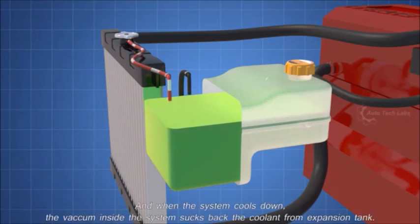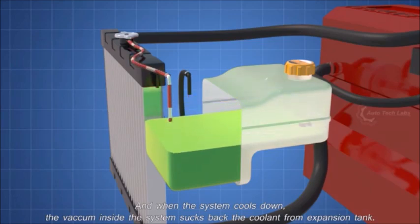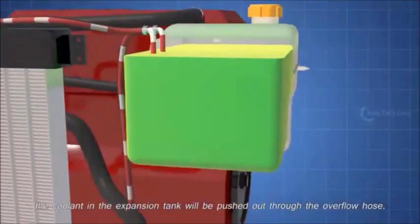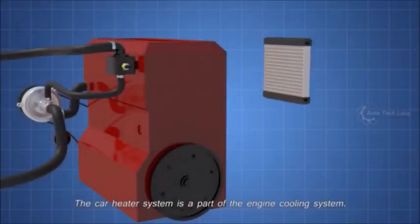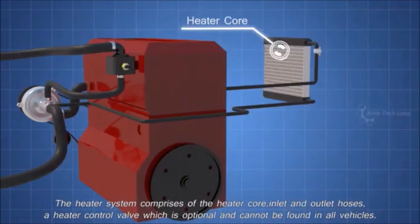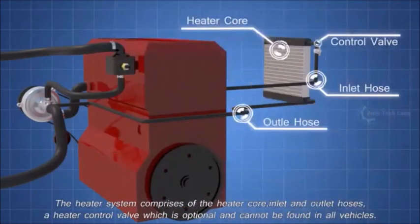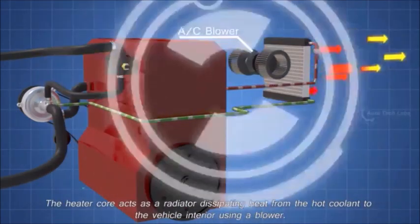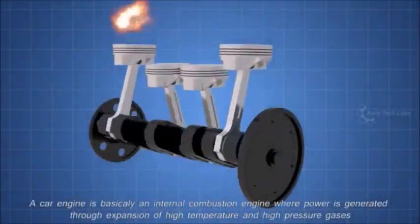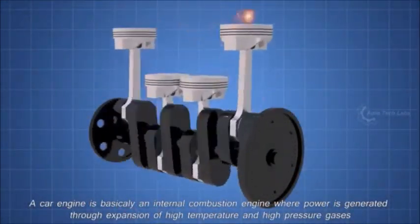Eventually, the coolant temperature increases by absorbing the heat from the engine. Once the coolant reaches a higher temperature, which is usually between 160 to 190 Fahrenheit, the bypass valve will start to close and the main valve will start to open. This allows the cold coolant from the radiator to flow to the engine side and the hot coolant from the engine side to flow to the radiator. In most cars, the coolant temperature sensor is located near the thermostat housing.